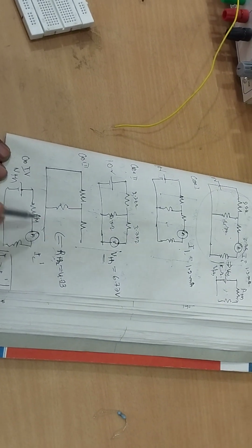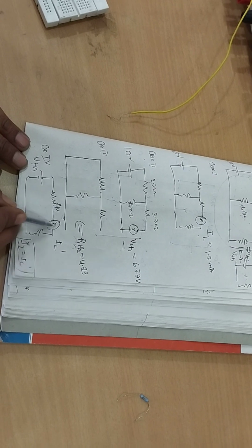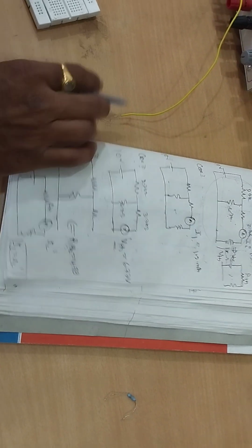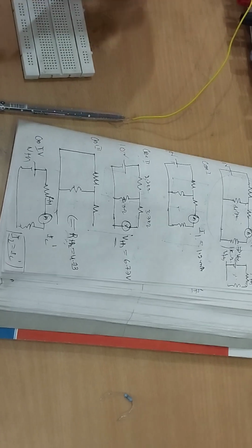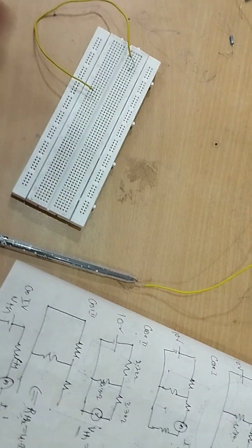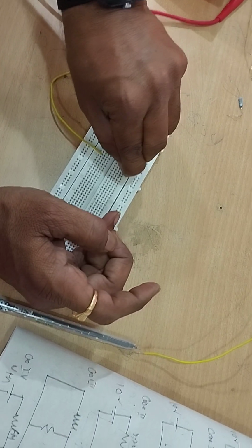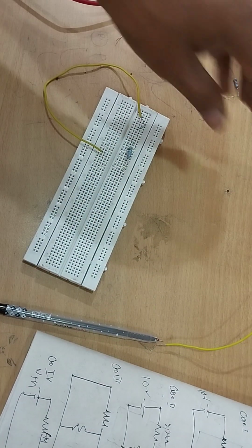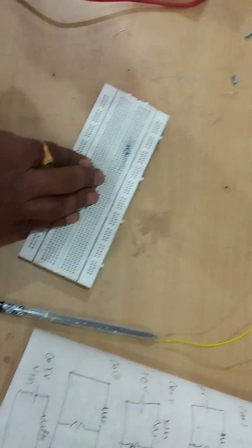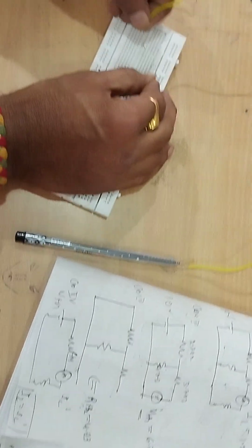Now we can successfully connect. We know the value of V Thevenin, we know the value of R Thevenin, and the response is to be taken in series with the load. So I will replace all the resistors and keep only one resistor, which is 4.7, the R Thevenin. I will keep this R Thevenin here. Remember, the input voltage given in the equivalent circuit equals the open circuit voltage we measured, 6.77. You need to set that voltage to 6.77.